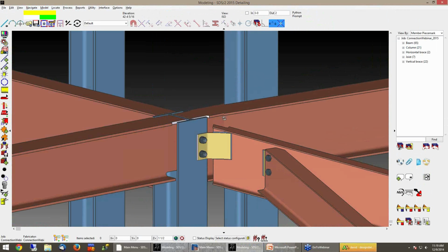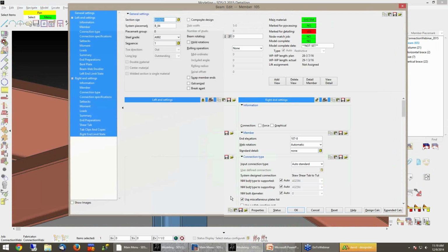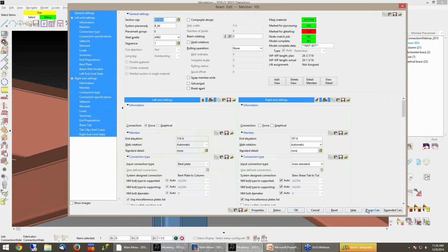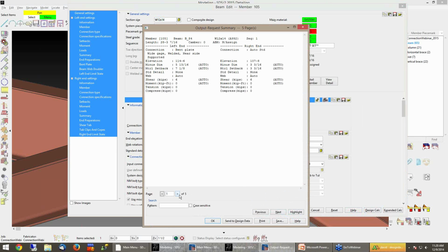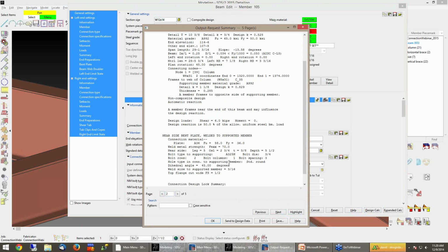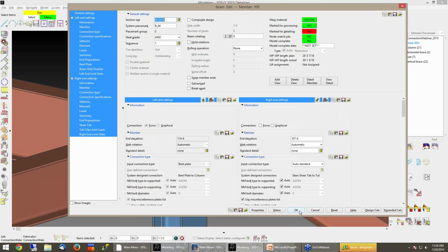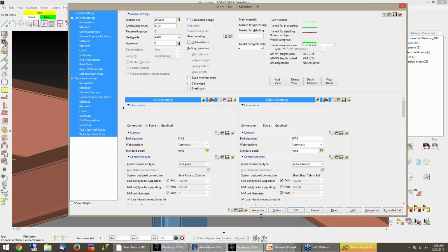With forced connections, force is kind of our user in a sense now, relating back to the design calcs. Because now if I force a connection and I look in the design calcs, I do have a forced connection note in here to indicate that the connection was forced to get what I wanted. So forcing connections will give you a note similar to the user connection in previous versions.